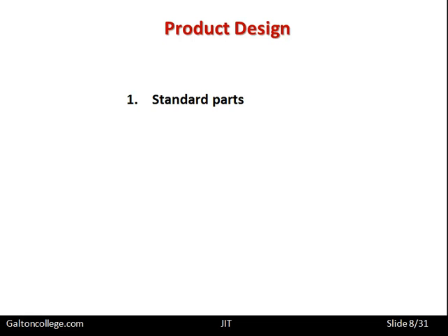Standard parts enables, in a sense, standard production processes. The production processes can be then linked one with the next, so that there is continuity of production from start to finish. But it'll only happen if the parts are standard. If each order coming into the company requires some variation, that of course will prohibit the introduction of JIT.